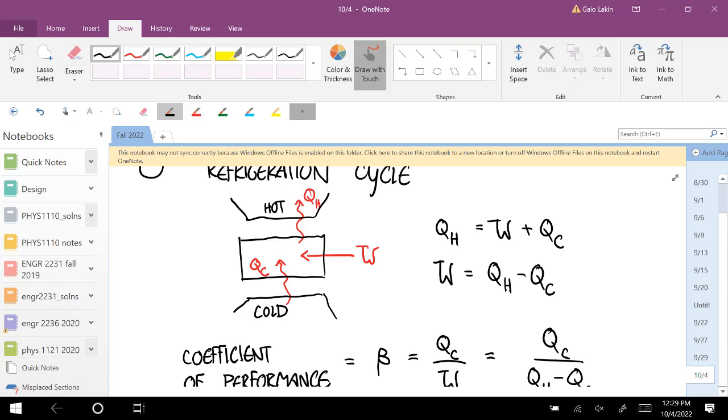If you want to get energy out of your system and into that hot reservoir, you compress that piston, get the temperature up, then remove the insulation, let it be in thermal contact with that hot reservoir. If you compress it so that the temperature is 100 degrees, then you're going to lose energy into the hot reservoir, okay? Now you insulate again, let it expand enough that the temperature in there is lower than the temperature of the cold reservoir. Let it be in thermal contact with the cold reservoir, and now you get energy flowing in from the cold reservoir. And so with that system of constantly expanding, bringing energy in from the cold, compressing, letting energy out to the hot, you can get this energy moving from the cold to the hot. But the cost is the work that you have to do to compress it and let it re-expand.